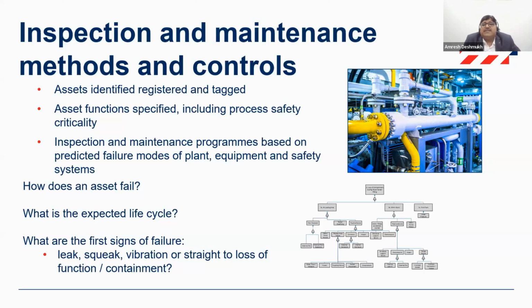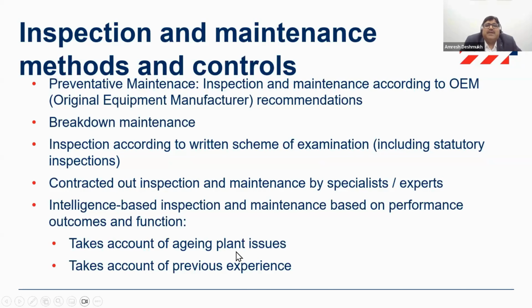We have also come across events where the pipe had some cracks, some minor cracks, and those cracks actually evolved into full-blown failures for the pipeline. So there are signs that you may get or capture from the field, either from your visual inspection program or from your predictive maintenance program, which can be inbuilt into your preventive maintenance strategy. Now, while you're doing that, there's some guidance that you get from the OEM as well, and the OEM also helps you with some preventive maintenance plan that he has with him, and you can use the recommendations given by the OEM.